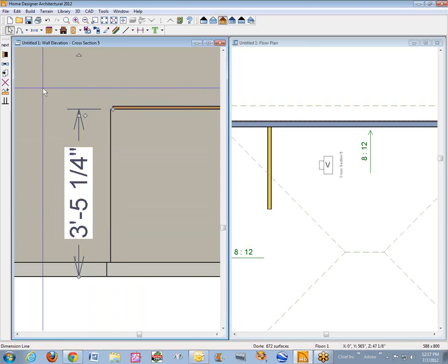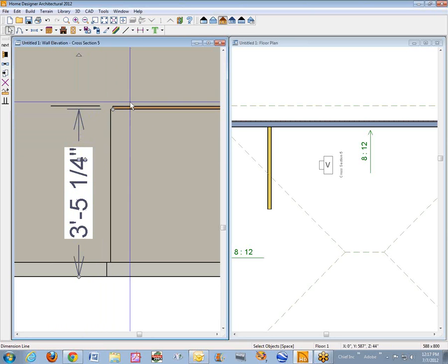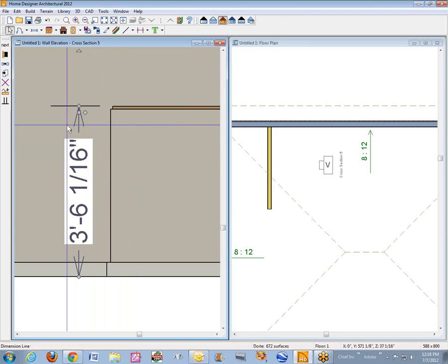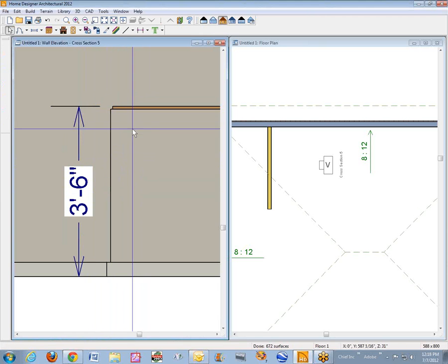Well, okay. You can call tech support, or what I do is go to CAD. I'm going to draw a line here. Just draw a line, and hit the space bar to get out of the line tool mode. I'm going to move this up to the CAD line. And then I'm going to click on the CAD line and then click on, see how my cursor changes to that little hand? Which should give me that dialog, and I'll put it at exactly 42. Okay, so now we've got a dimension. This is probably more than you asked for, but I'm just demonstrating, so why not?